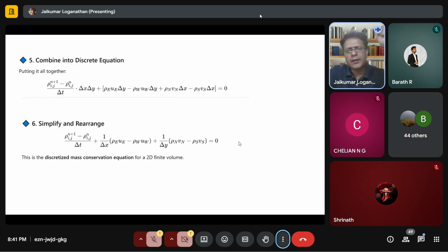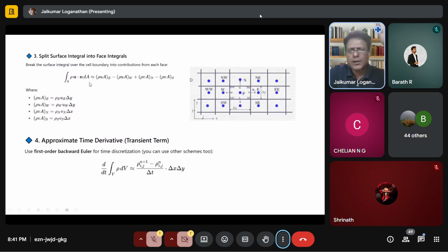then we discretize the domain so that the integrals can become a summation. Right? That is the main reason why we are discretizing the domain. So imagine you have a very complex geometry. By mesh generation, what we are trying to do is convert it into either a hexahedron in the 3D sense, or in 2D we may convert into a triangle or quadrilateral, because they become simple shapes on which we can convert an integral into a summation, right?